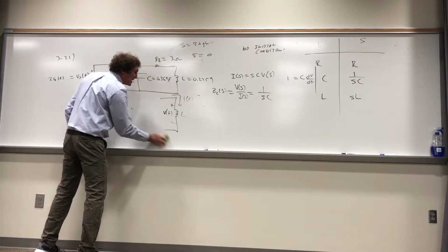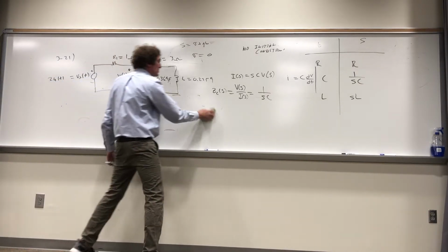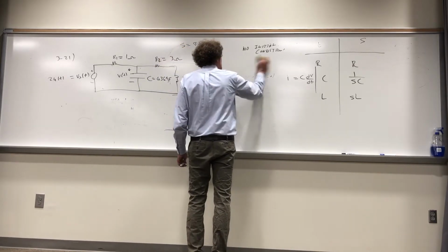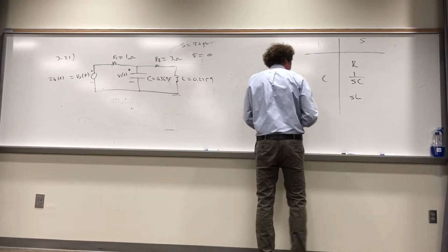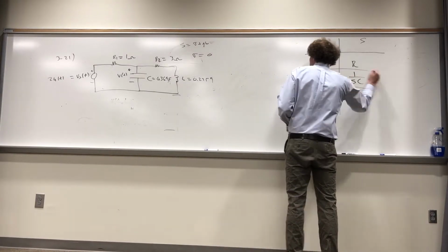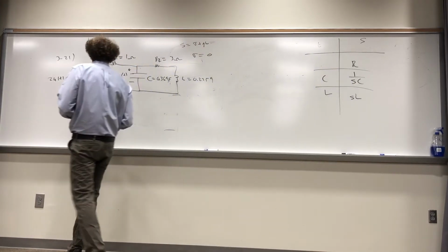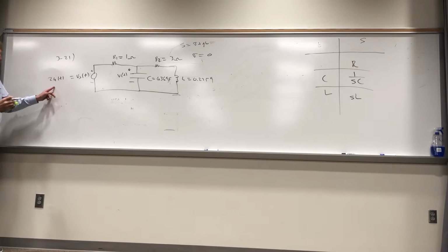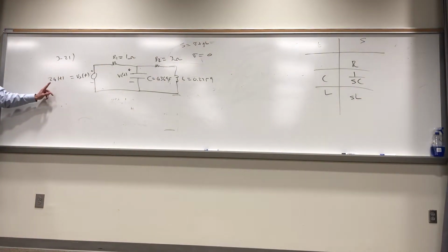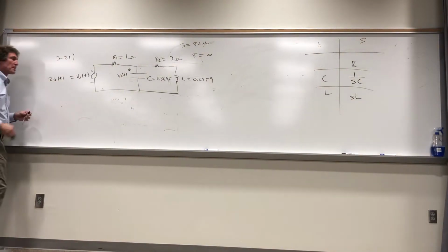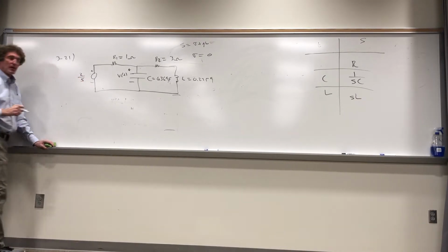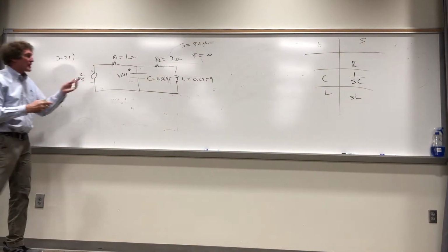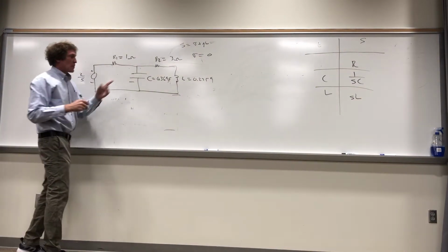This problem at least should look very familiar to you in terms of things you've seen before with circuits. I'm going to leave that up here. So now I have an impedance here of R, and by the way, do the Laplace transform of any kind of time domain function when you do this kind of problem. There's no initial condition. What's the Laplace transform of 2u(t), people? Just 2 over s. So put it in there, 2 over s. There's R. Now, they want v(t). Really what they want is the voltage across that, but we're going to put the impedance there.